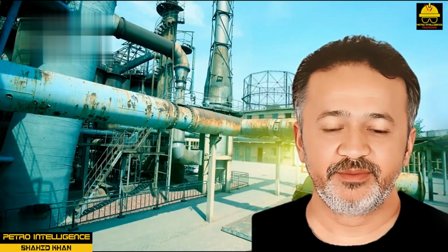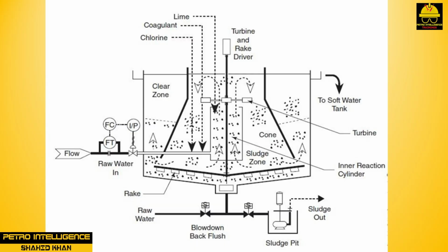Blowdown. Blowdown is a term used to describe the process in which water is removed from the boiler system. As suspended solids concentrate in the water, chemical treatment reaches a point at which it is no longer effective. Removal of a portion of the treated water is necessary. Blowdown depends upon the amount of suspended solids the boiler can handle.